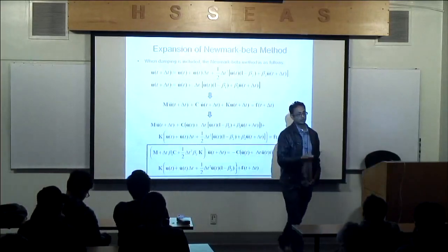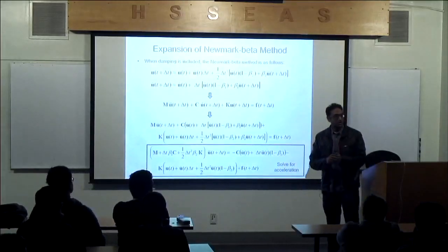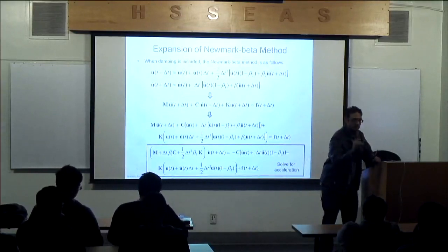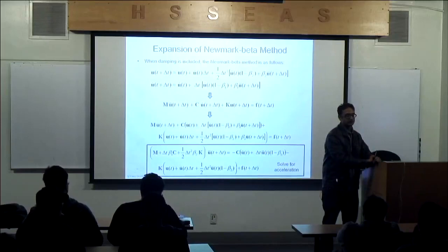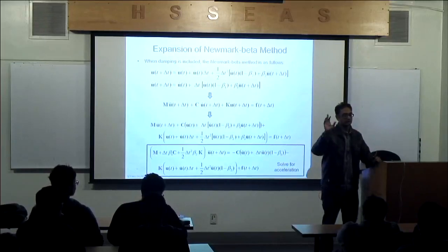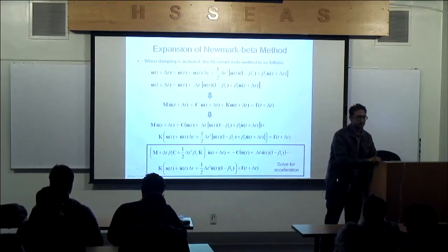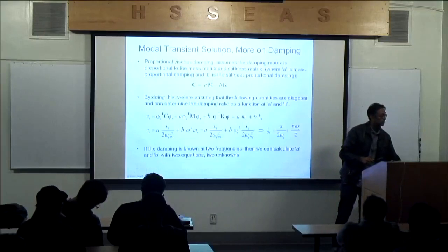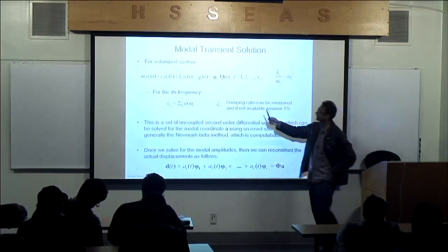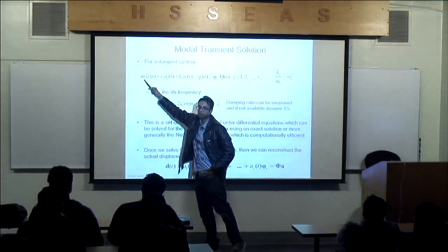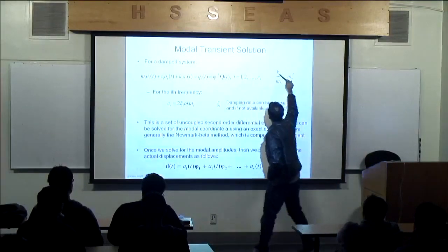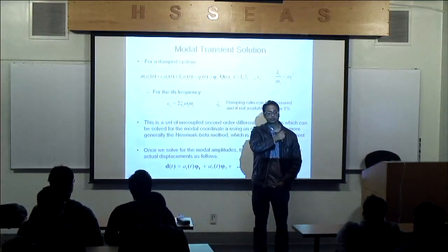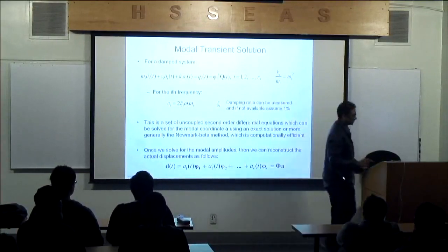Okay. Go ahead. So M is not a matrix? So remember, we uncoupled. We went from a coupled system to fully uncoupled. Everything's uncoupled. Just values: mass, damping, stiffness. And what's more incredible to me, and I may not have covered it, if I take the ratio of Ki divided by Mi, I get the frequencies. I get back the DNA of the system. That's what's amazing about this.